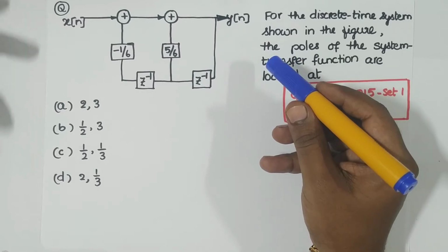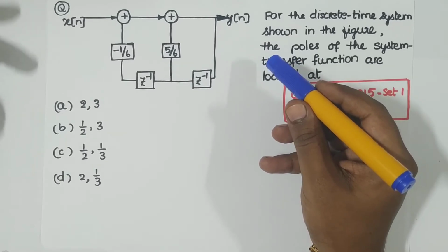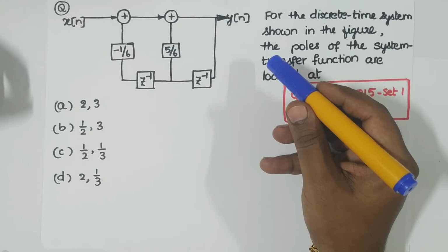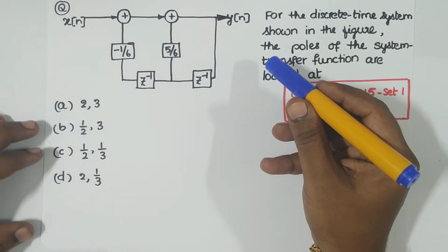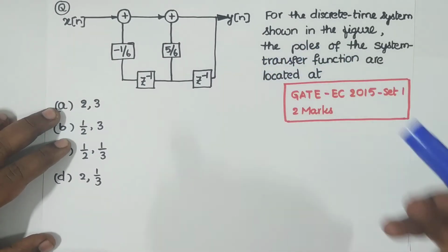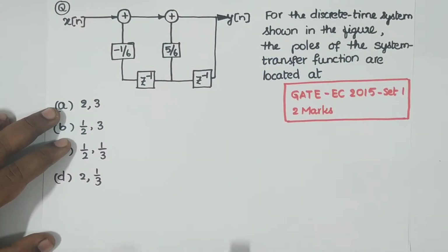There is no second thought. We obviously choose direct form 2 because it requires less memory when compared to direct form 1. And the same DF2 we use in cascade form and in parallel form as well, for further optimization of our discrete time system design.